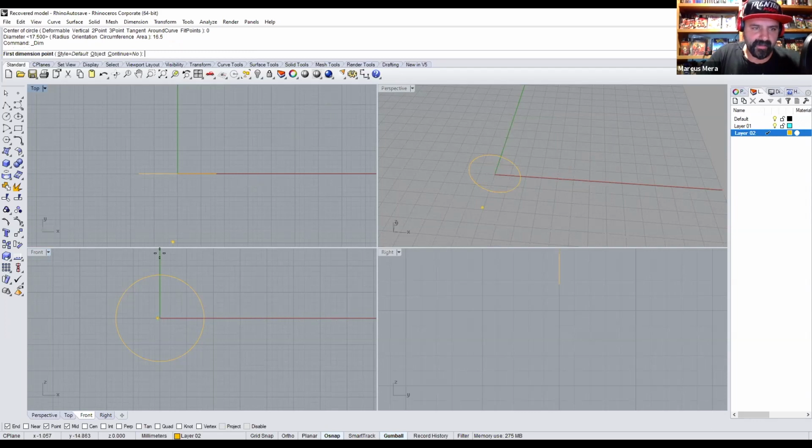Left click on that, and make sure your snaps are on over here. Down here, we have our on snaps. So these are the basics. We want to make sure that on snap is turned on. My arrow is down here. We have on snaps turned on, and we want to make sure that we are set, for this purpose, to quad. Now, if I right click on quad, it's only going to select the quad, nothing else. If I left click on an option, it will add to the selection. So now I can select end, or instead of end, why don't I select center?